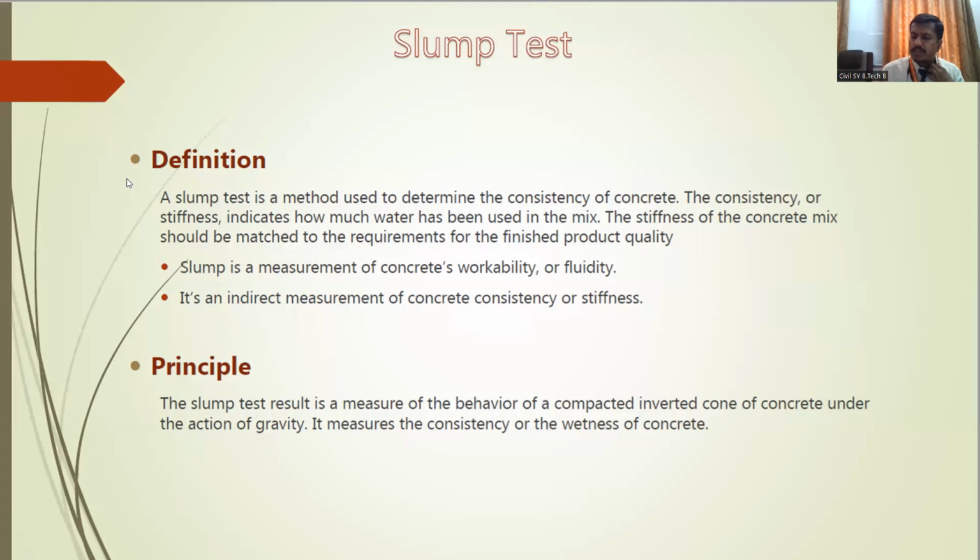The top diameter of the cone is 10 centimeter, bottom diameter is 20 centimeter, and the height of the cone is 30 centimeter. You are going to fill the concrete in the cone in 3 layers by compacting.